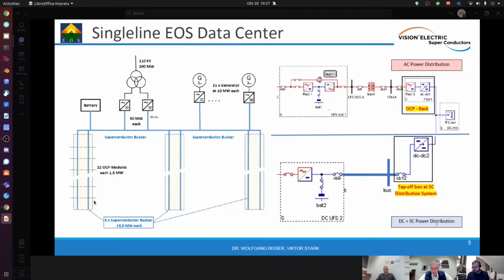And in most data centers, the problem is not the supply voltage, the problem is the ground voltage, and therefore in a lot of cases you normally have a double ground wire, double ground cross section, because the ground is in most cases the critical point. And especially in a tier 4 data center with an A and a B supply, you normally have a potential difference between A and B, and this is not the case with superconductors.